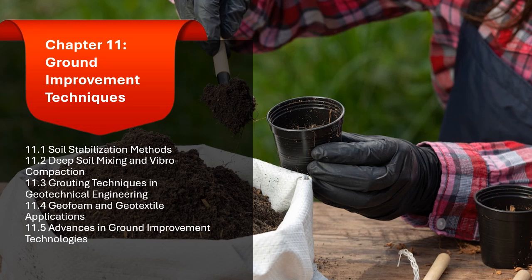3. Monitoring and quality control. The grouting process is closely monitored to ensure that the grout is being injected at the proper rate and pressure. Various testing methods such as grout injection pressure and volume are used to assess the effectiveness of the grouting process.